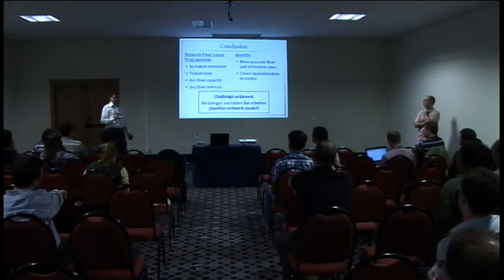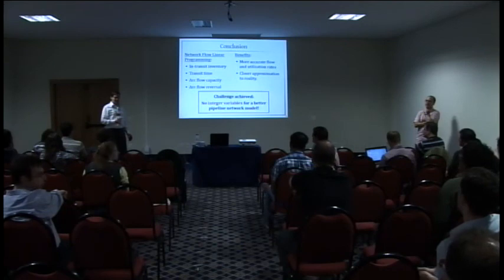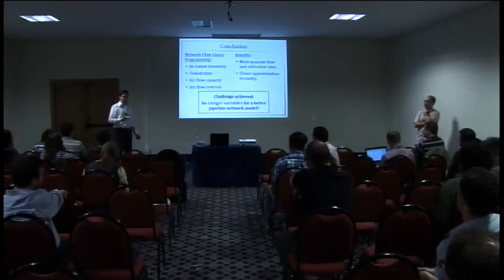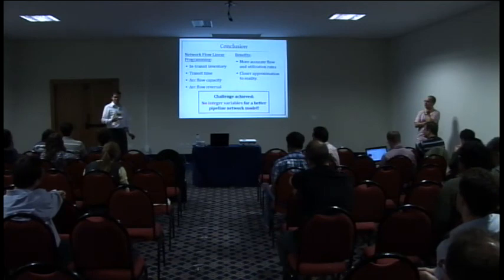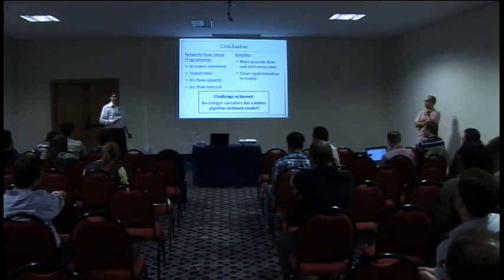We know for 2 months, 8 time slices is a good number, but we still have to study this more to understand how it behaves. For example, I know that 1 time slice per day is a bad option. It generates a huge model that doesn't fit the memory of the computer, and it starts violating the relaxation.